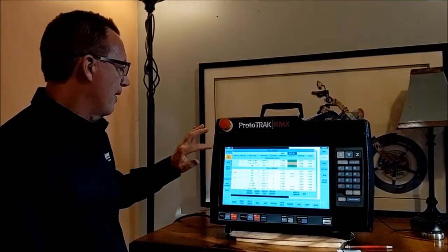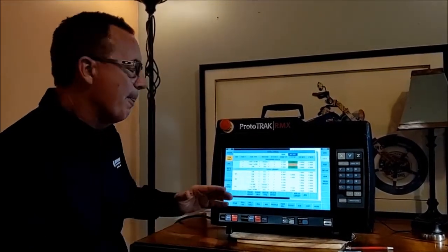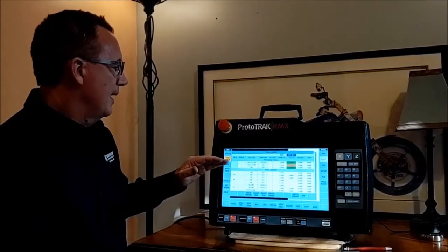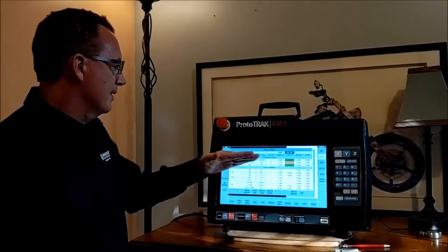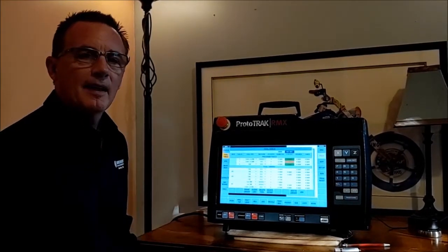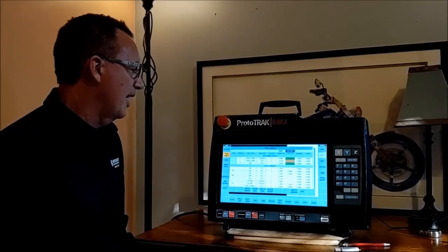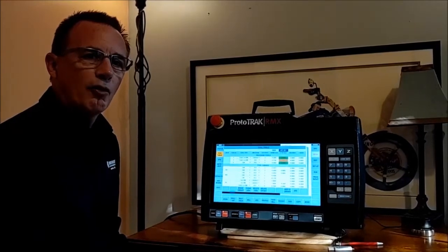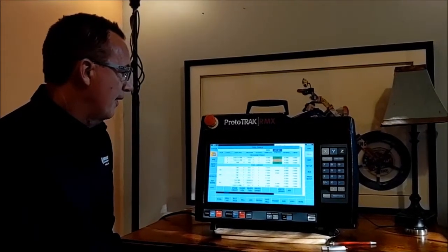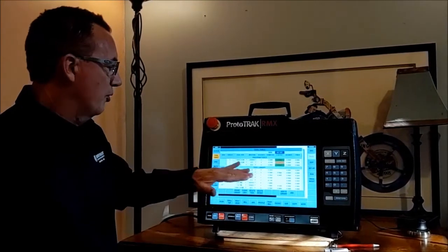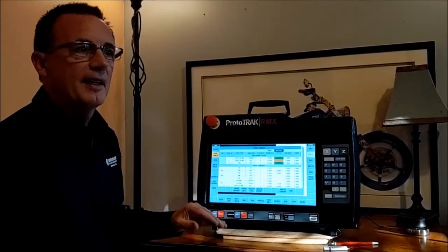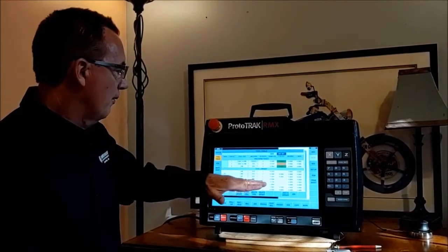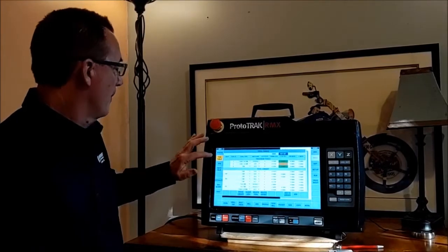The tool table is a really cool feature. It has 3 parts to it, and the base has to be set on a milling machine, and so that's the first part. Once you set that base, you have a program tools, which is the second section of the tool table. This is where you'd fill out the tool description that goes along with your program. And the third section is the tool library, and this is where we can put tools into the library, or we can take them out of the library and put them into our part program. So it's a very cool feature. The library is new for this control.